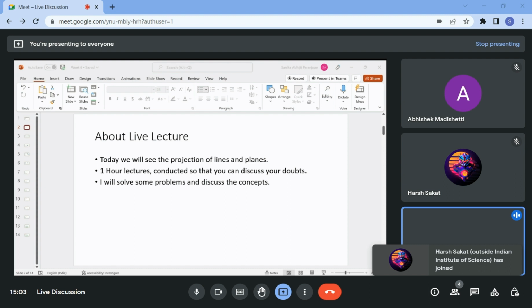So if I'm having an angle like this and I have a plane like this, then this will represent a true angle. As soon as I rotate it like this, the plane no longer shows the true angle of this line with respect to HP. So I will have to have a plane which rotates with the line in order to see the true angle at all times.